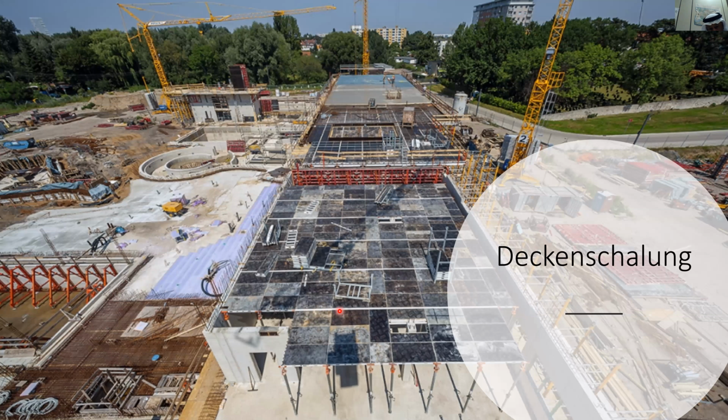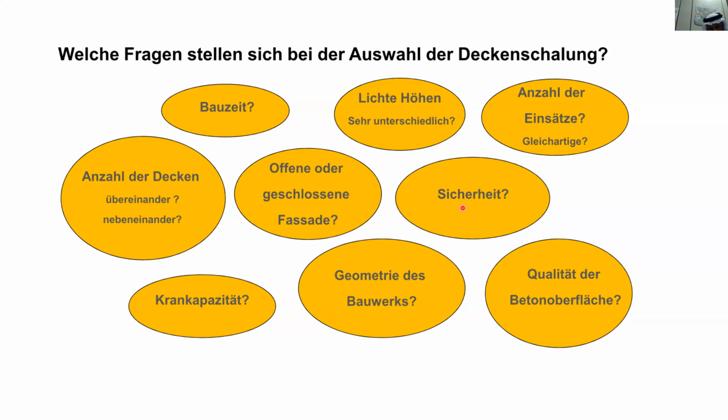And last but not least, it's also a topic of what's the quality of the concrete surface. Yes, so looking at a concrete slab from down under, looking to the concrete floor above, what will be the surface? What's the architect's wishes? So I have to ask these questions before I choose the correct formwork.